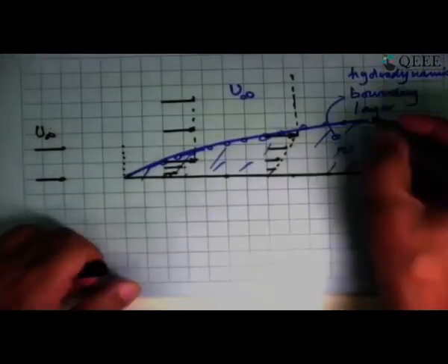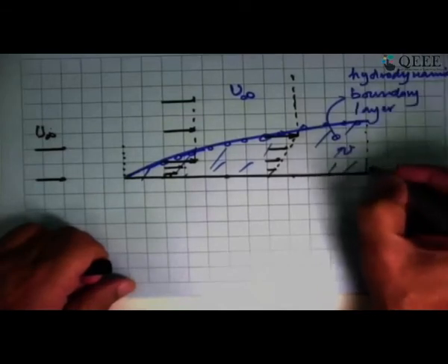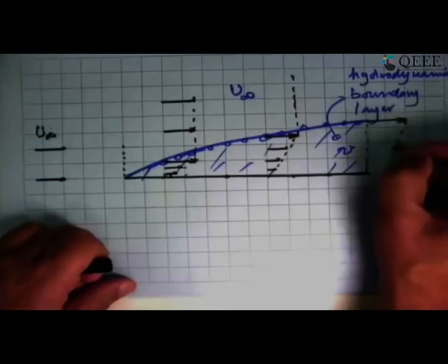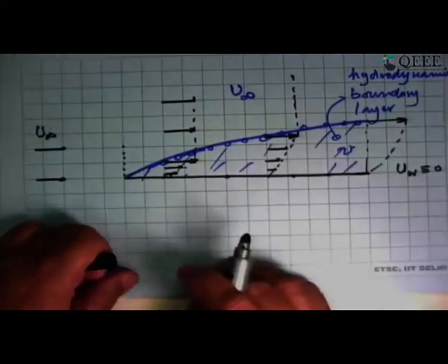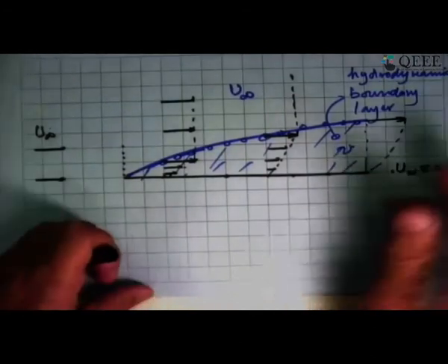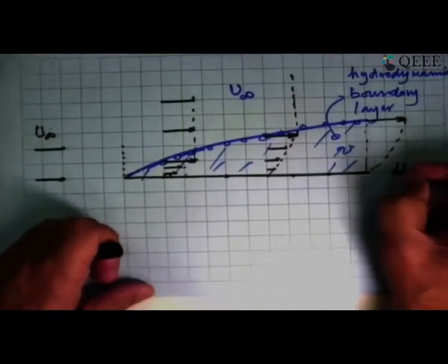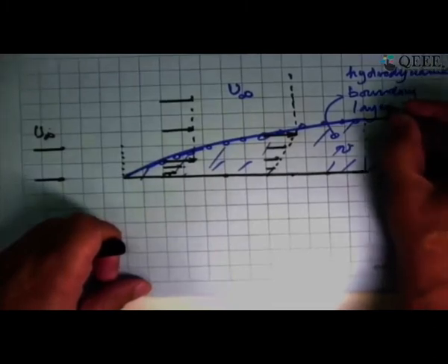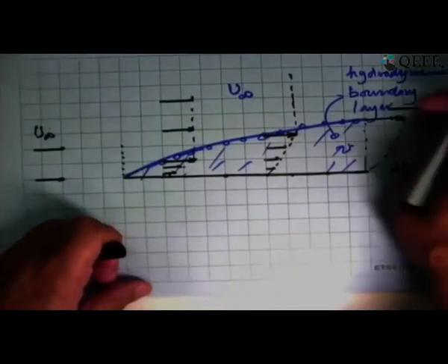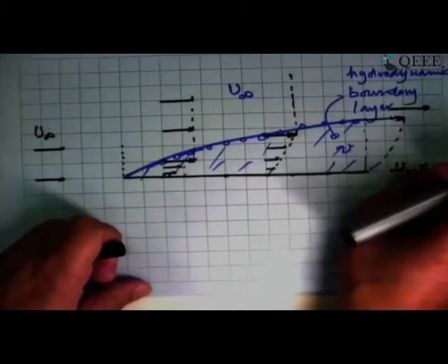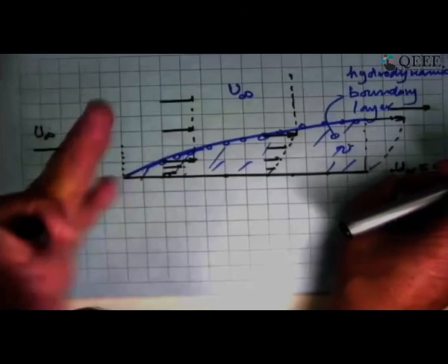But what happens is, in this plane, the velocity here was 0, velocity here was u infinity. So you have a velocity profile like this, and further down, there is no plate anymore. So this element which was stationary, gradually it begins to get a small velocity. This element is dragging the next element down. So this dimension grows, but this velocity at the center slightly increases.